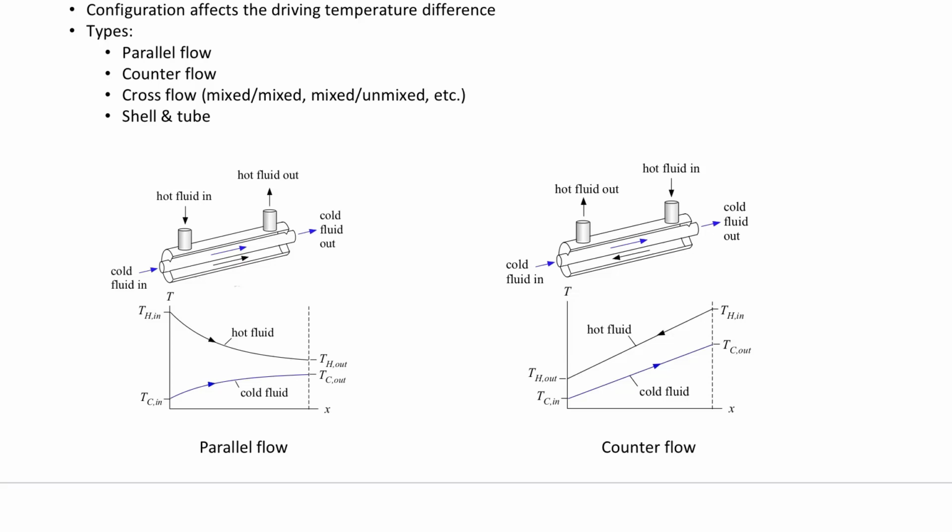So you can contrast that to something that is actually more common, which is the counterflow. In a counterflow heat exchanger, you have hot fluid coming in. Now the hot fluid's coming in to the back side here. The cold fluid's still coming in on this side. And the flows are kind of doing this, right? They're crossing each other's paths. So the interesting thing here is, one, you don't see this kind of exponential decay due to the loss of heat transfer. You actually see that the thermal profiles on either side are pretty linear. It's not exactly linear because the heat transfer corresponds to that delta T wherever it is, but it's pretty linear. You're getting a pretty constant heat transfer rate as a function of position.